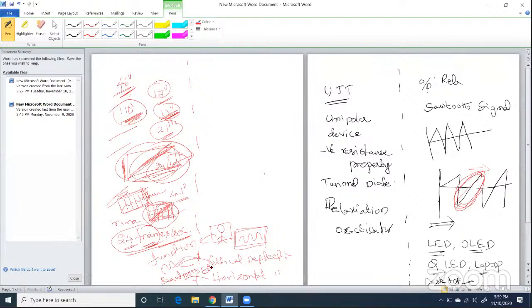You can observe the block diagram. You can find the block diagram for any display. You can find the vertical deflection plate and the horizontal deflection plate. These two deflection plates combined induce the picture or waveform across the screen. For the vertical deflection plate, the direct signal is connected, and for the horizontal deflection plate, the sawtooth signal. This is the signal sweeping the waveform across the screen.